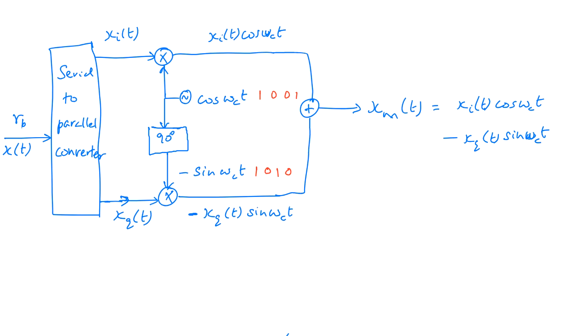That's one combination that the two carrier waves can have, 1 1, or another combination of 0 0, or one is 0 and the other is 1, or the first one is 1 and the other is 0. So with four combinations we get the four symbols: 0 0, 0 1, 1 0, 1 1, right? So that makes it M equal to 4.